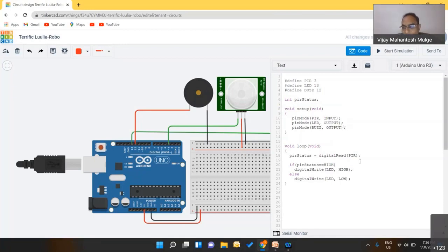So what will I do? Wherever you have written this LED pin, I can include the buzzer there. So I can write digitalWrite. In parallel, we are turning on both things. So here it is buzz, followed by HIGH. And you can use these braces here.